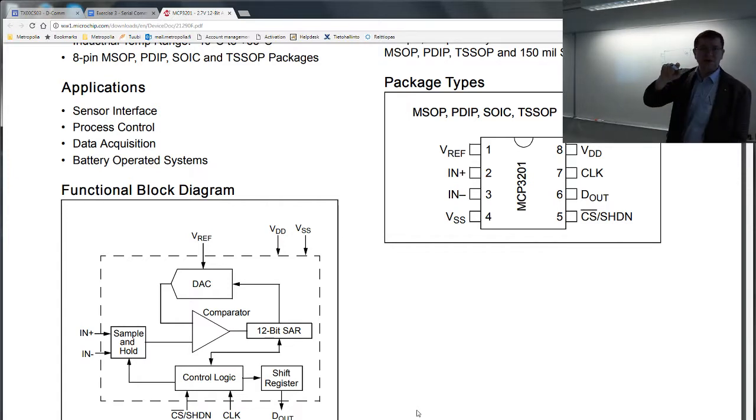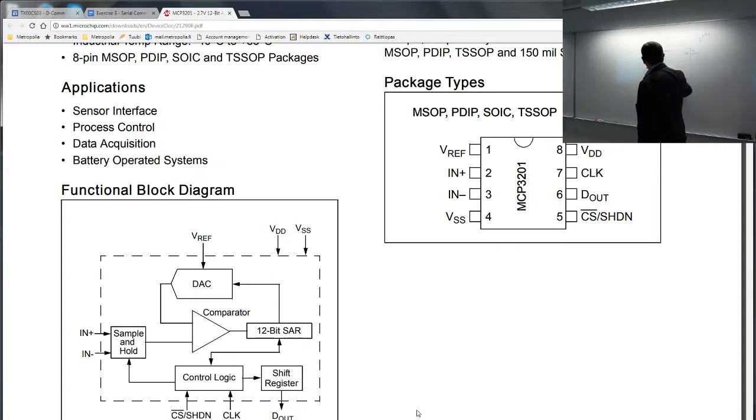Okay, the input minus signal is the local reference, and this actually gives unipolar digitized data compared to this one. So basically this gives you the lower limit of the A to D range. Most of the time this should also be connected to VSS.